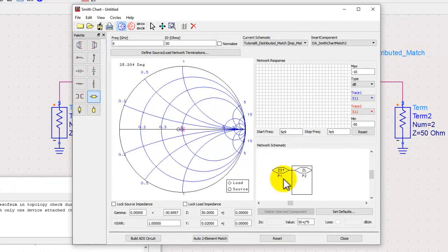So we'll go ahead and insert a line, and that line, because it's by default 50 ohm, will get stuck there. So I will click on this line, make this impedance slightly higher, let's say 70 ohm, and then I will give it some length, for example 20 degrees, and now I will have some line moving in that direction. So first criteria fulfilled, 20 degrees will be just sufficient to launch an SMA line.